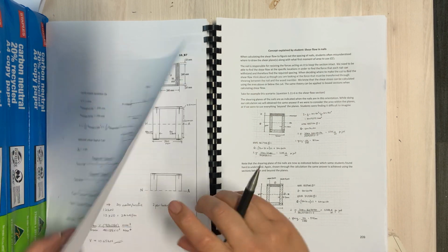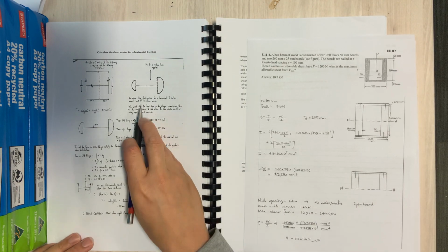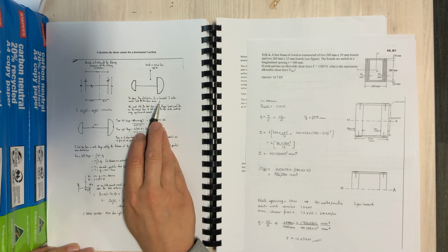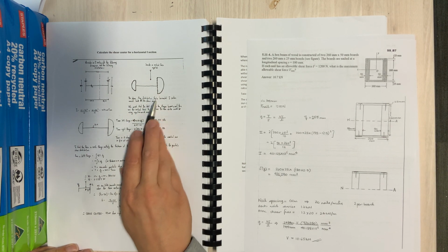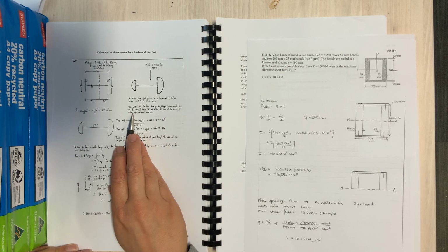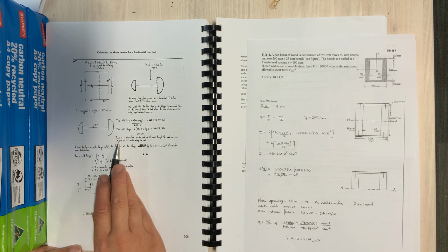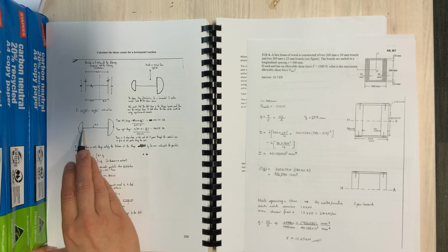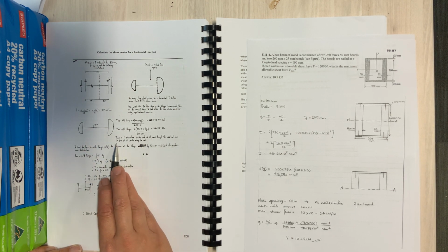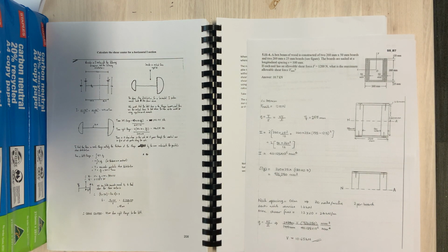The former student, who very kindly wrote this out, has provided some notes. The shear flow distribution in the horizontal I section will look like this. We must find the total load in the flanges, and then we use the vertical force to work out where the shear center is. There is zero shear stress in the web, as it passes through the neutral axis, i.e. y0 at all parts along the web is equal to 0.